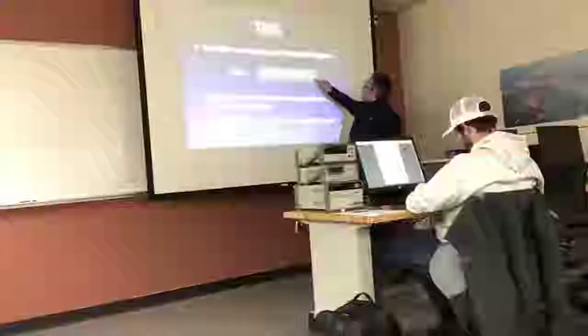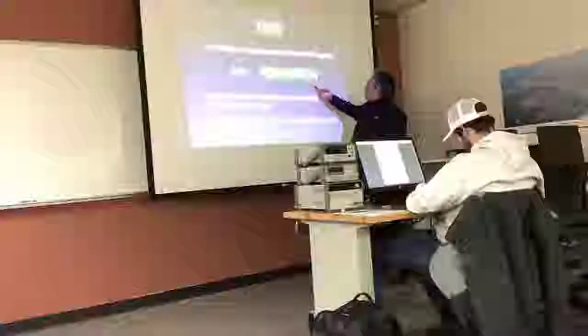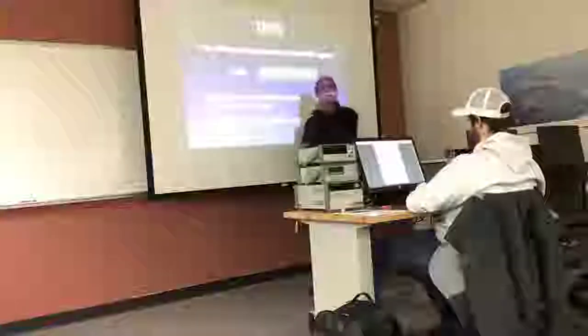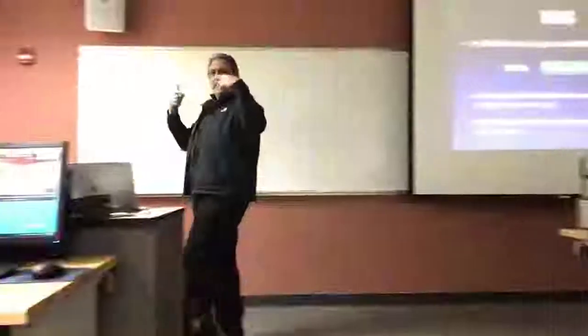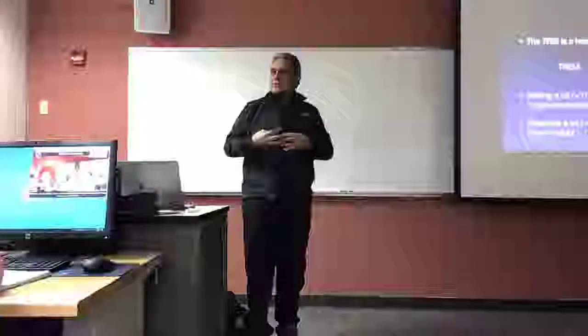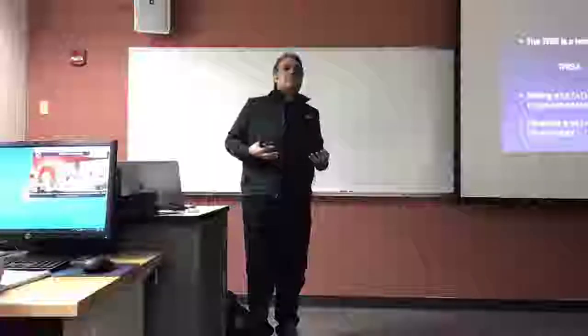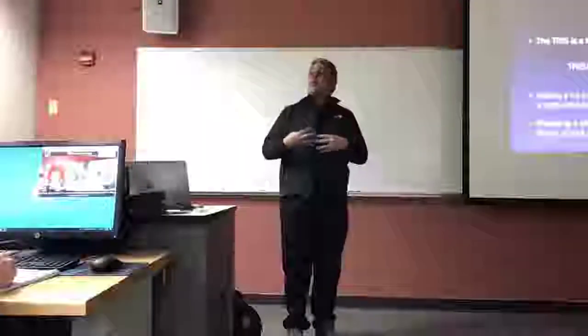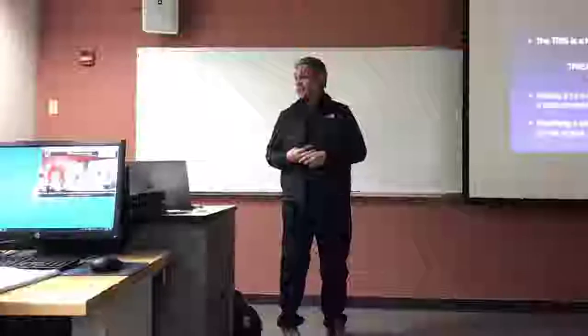So what we're going to make it is that if you put a 1 on this specific pin, the actual physical pin 2 will become a high impedance input. Now the word high impedance should kind of give you an idea on how your multimeters actually work. The high impedance is actually a feature of your multimeters so that they don't consume current and change the actual electrical characteristics of what I am attempting to read. Right? Think about it. If I have an electrical system and I connect something to it that draws a lot of current, I am going to change the characteristics of what I am attempting to read. So I'm going to be reading something that is not right.